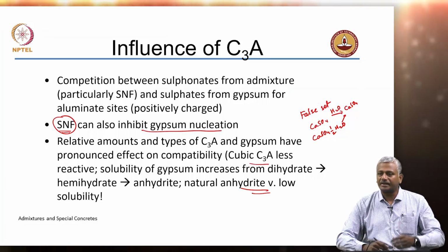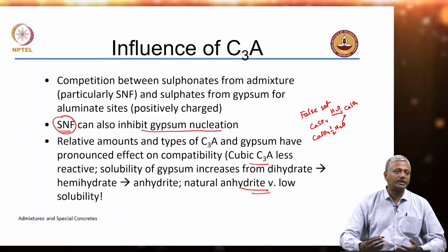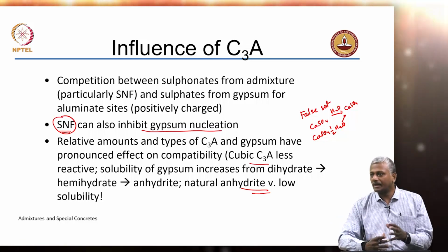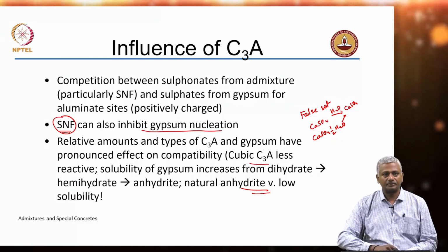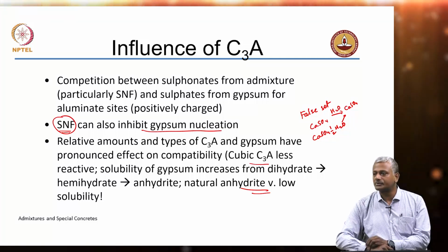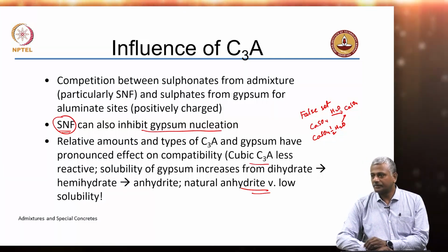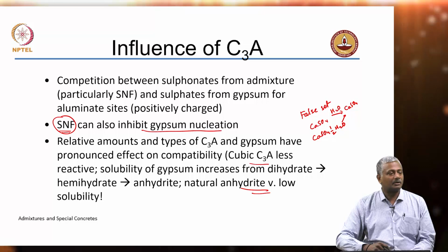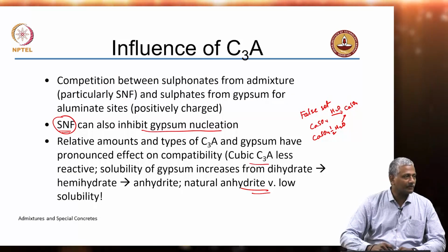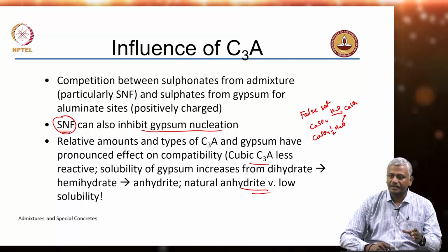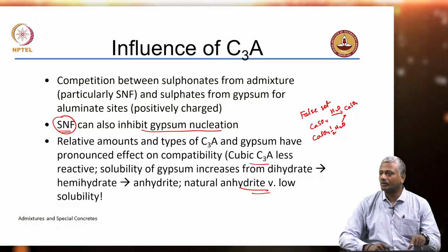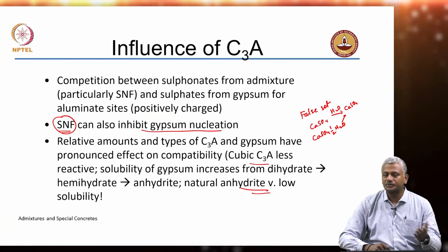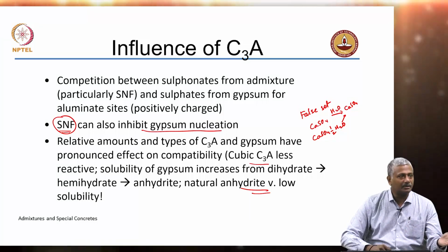Now just to take a step backwards, in cement chemistry all the reactions happen because the ingredients of cement start dissolving in the water around and recombining to form the hydrated phases, okay. So obviously the dissolution of the cement compounds is a very important step, right. So anything that prevents a dissolution will retard, anything that accelerates a dissolution or speeds up the dissolution will accelerate, okay. So here what is actually happening is the inherent solubility or reactivity of the material is responsible for its availability in solution to do the reaction. So C3A in one form is more reactive than C3A in another form.